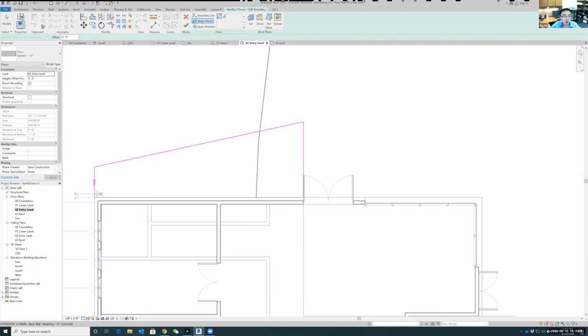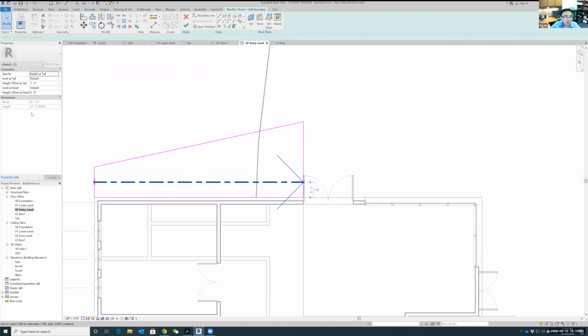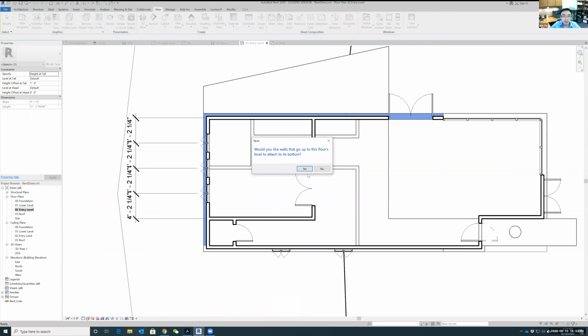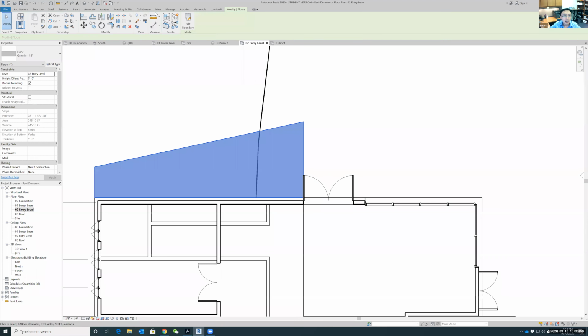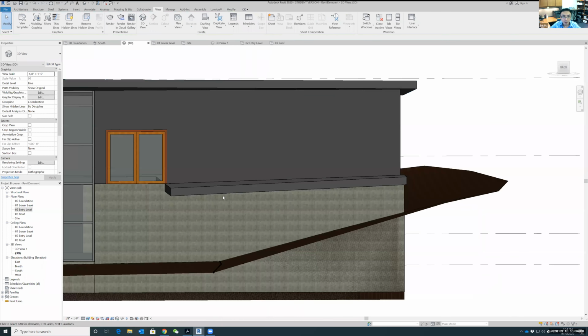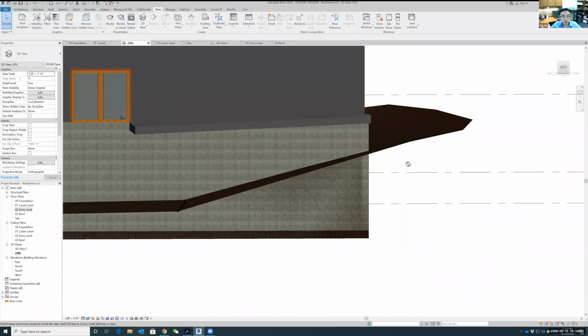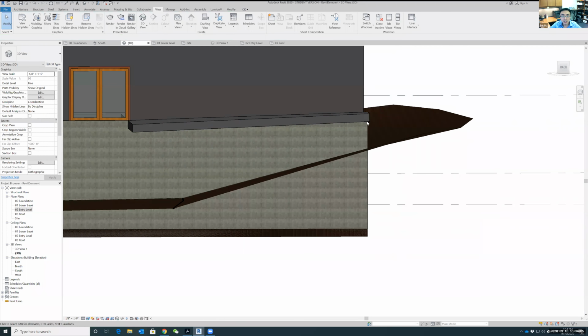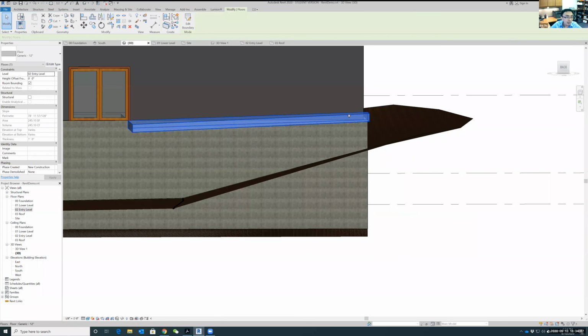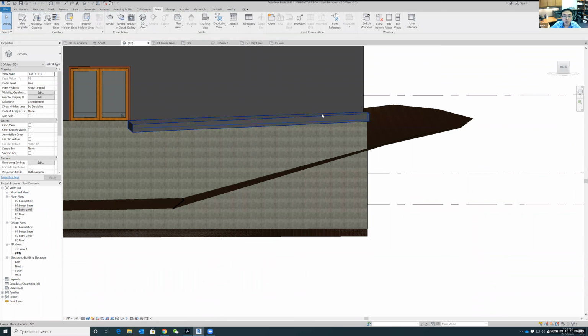So I'm selecting this one and just draw a big arrow. The arrow will define the slope, okay? So I'm just drawing a big arrow here from here to here. And this one defines a slope. I'm not quite sure what slope I need, but I can see. So I just click OK. Click no, and let's see what's going on. It's actually going the wrong way. So this side is higher, okay? So I select this one. I want to change my slope.